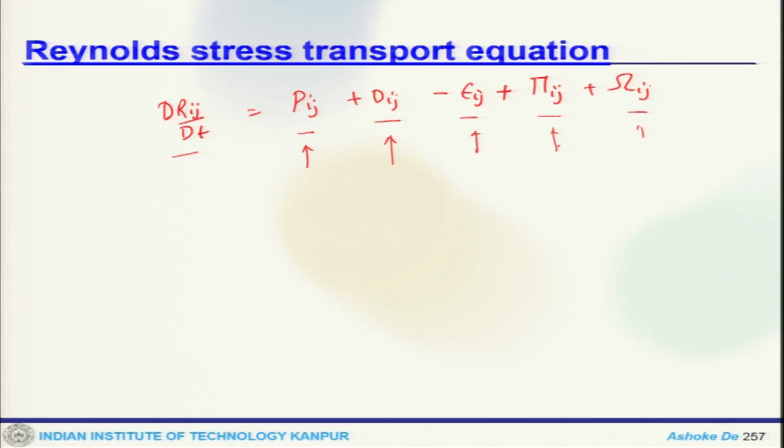The pressure strain interactions are quite important because this actually includes pressure fluctuations due to eddies interacting with each other at different mean velocity. So the overall effect is to make the normal stress more isotropic and to decrease the shear stresses. So it does not change the total turbulent kinetic energy. This is one of the terms which is very difficult to model, and various models are available. Common is the Launder model, improved nonlinear, and finally this term is the transport due to rotation.